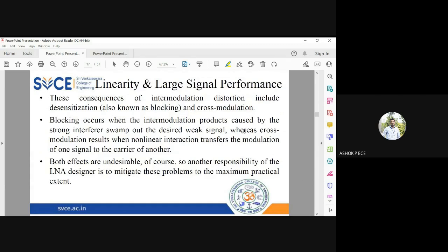What all can cause noise? So we have seen IM distortion, intermodulation distortion, IMD. In the last class, we have seen what is IMD. The harmonic distortions will take the form NF, integer multiples of the fundamental frequency. Intermodulation distortion will take the form, since we are sending a two-tone signal, of a linear combination of these two frequencies, MF1 plus or minus NF2. This is going to be IMD, the intermodulation product.